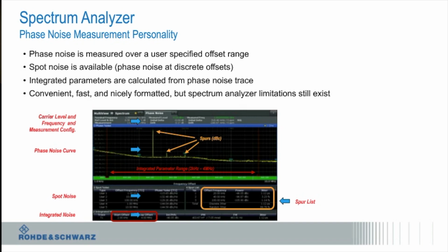Away from the carrier, just over that region, right? But some guys care about a particular offset, right? In that case, you would say, what's the phase noise, not the integrated phase noise, at 1 kilohertz offset from the carrier? Or what's the phase noise at 10 kilohertz offset from the carrier, or 100 hertz or whatever? Typically those guys would get multiple numbers. But then some guys want the integrated, so they just want one number that says, tell me everything all added up together over that entire range.